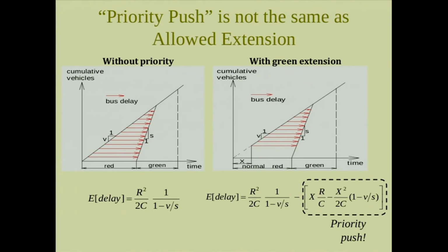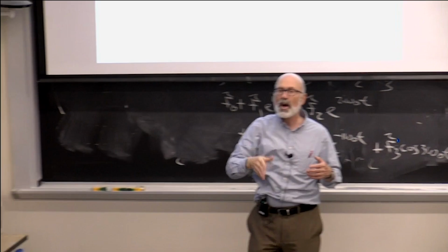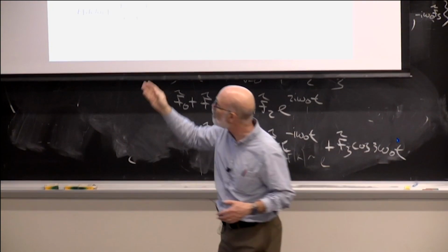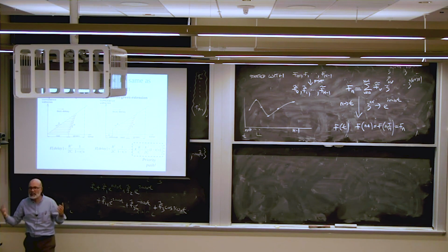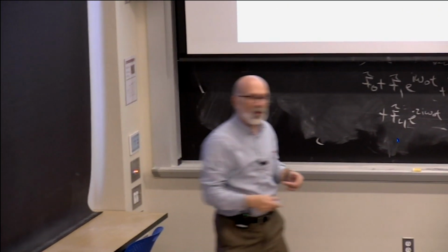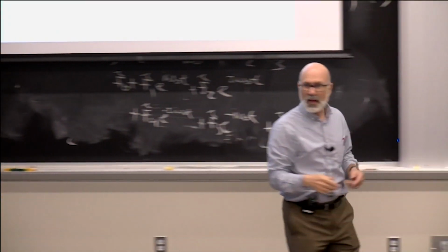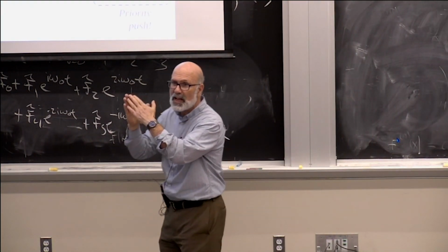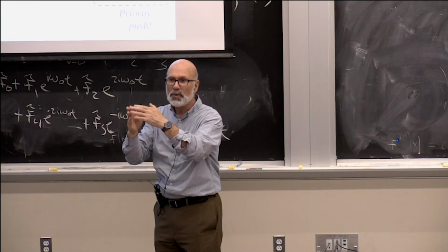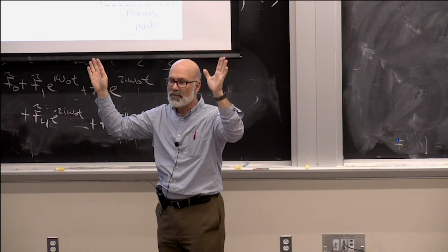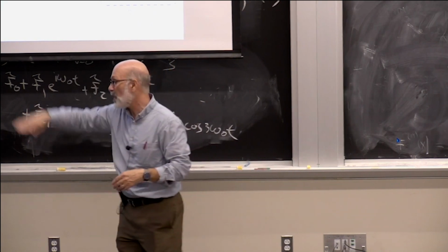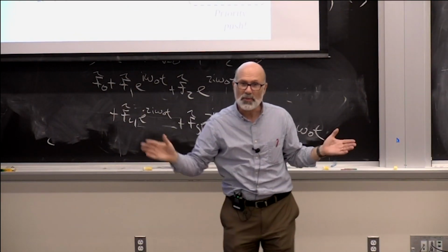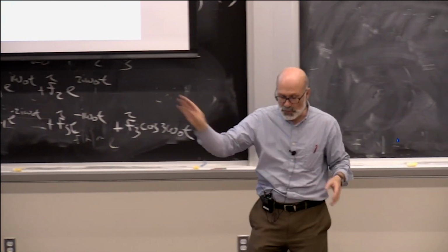So this line has a slope of about 1 car every 2 seconds as they depart. This is as they arrive, maybe 1 car every 5, 6, 7, 8 seconds. And where the 2 lines meet, that means the last car in the queue is now gone. And after that, as cars arrive and depart without joining a queue, they just go through.